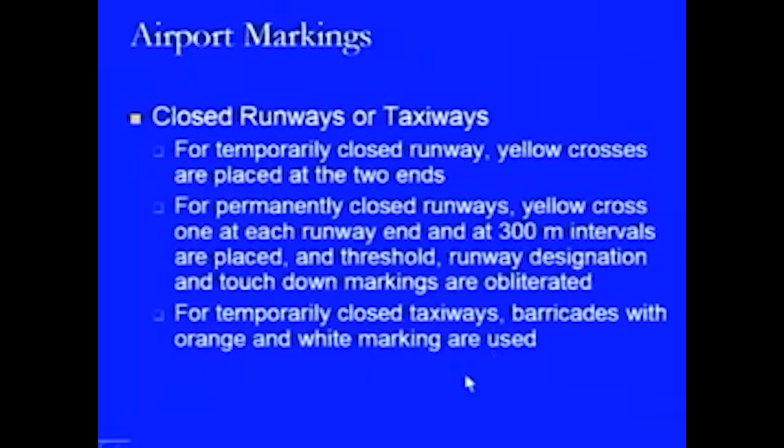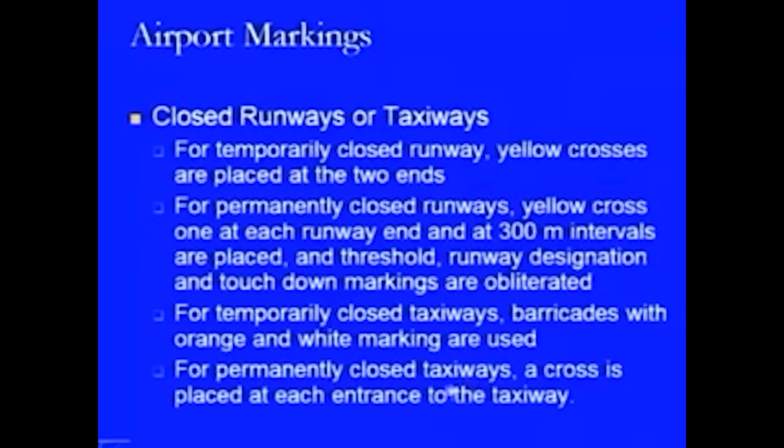For temporarily closed taxiways, barricades with orange and white markings are generally used. In case there is a permanently closed taxiway, then a cross is placed at each entrance to the taxiway. This is the way generally we do the closed runway or taxiway marking.